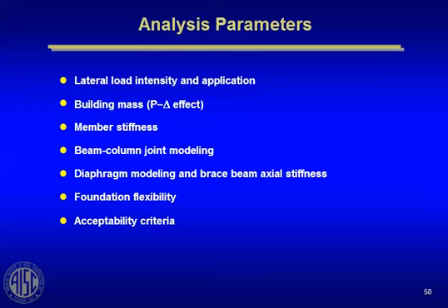A simple assumption, rarely true, very conservative. Every foundation has a certain amount of rotational resistance at its base, whether it's sitting on a spread footing or whether it's sitting on a pier. Whatever it's sitting on, it's got some rotational stiffness. And the reason you should count on that is because if drift controls the design of your building, the worst drift condition you'll have is probably in that first story.